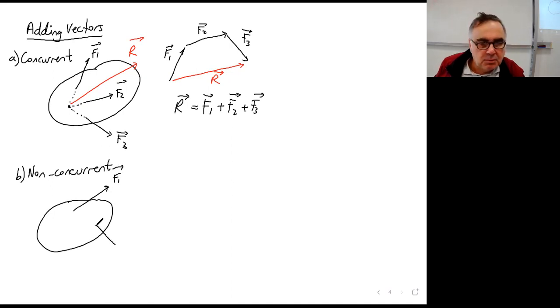This is F2. Well, two forces always meet at a certain point, but there might be a third force that is totally irrelevant. So these are non-concurrent forces. You cannot make them meet at a single point. So you can take a point here in the body, about a point O, let's say.